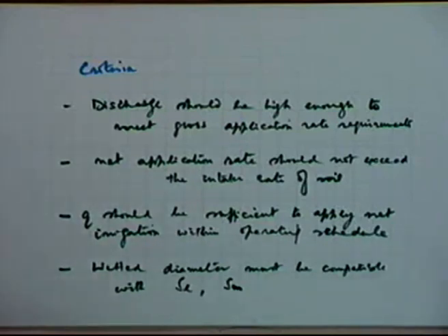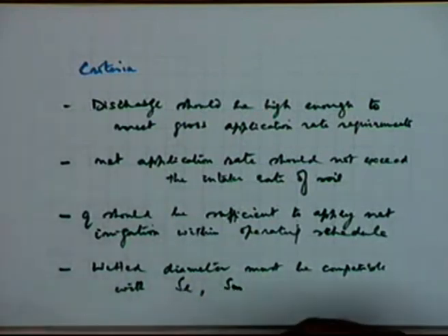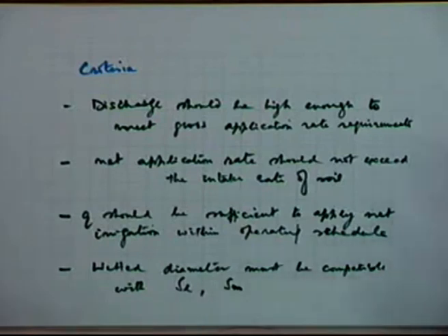It is dependent on the nozzle. And you have to have compatibility between the spacing and the wetted diameter, because we have said that there should be a minimum overlap of 6 meters. Now that overlap of 6 meters will come only through the overlap of the wetted diameters, and the overlap will be decided also by the spacing which you have utilized. So this spacing is also related with the type of nozzle which has been selected.